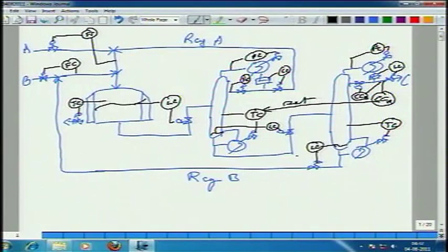Do you see what I am saying? So, it is not enough to say I want 99.9% pure product. That 0.1% impurity, what is it? How much B, how much A? Okay. The B is being set by the reflux in the second column, the A is being set by the first column. Yeah, this must be understood.